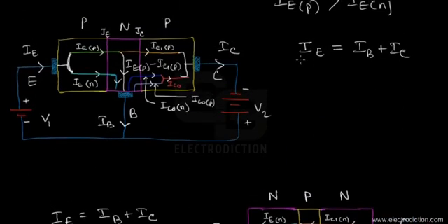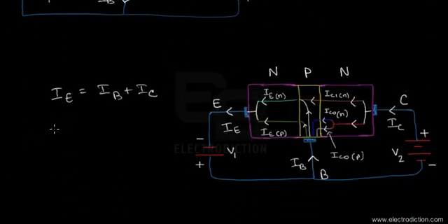Okay, now apart from this, we can also see that the collector current IC is of course composed of the reverse saturation current component ICO plus the majority carrier collector current component, that is IC1P. Similarly, we can also see that over here the collector current comprises the reverse saturation current component plus the majority current carrier component present in the collector, that is IC1 due to the electrons, represented with IC1N.